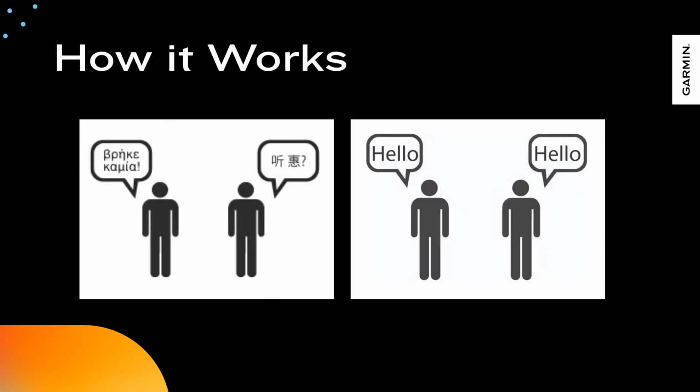Even if two devices are using ANT, they still may not be able to understand each other. ANT+ leverages the network key and device type channel parameters to help solve this problem. If you recall from the ANT crash course, the network key is used to uniquely identify a network. ANT+ is a managed network, meaning it has its own unique network key and there are defined rules and behaviors governing its use. The device type field is used to differentiate between different types of ANT+ devices.